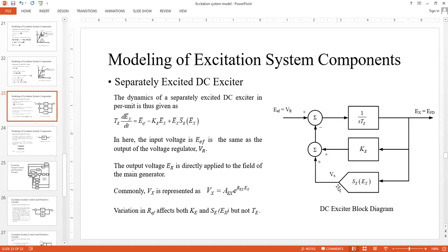Of course, after this is being linearized, then we simply add them. This is already in linear form, this is in non-linear form. So you linearize this, you simply add these two, and you apply the negative feedback formula for block diagram reduction. So what I'm talking about is this. We are simply looking at the block diagram reduction technique for this overall thing, after this is being linearized.